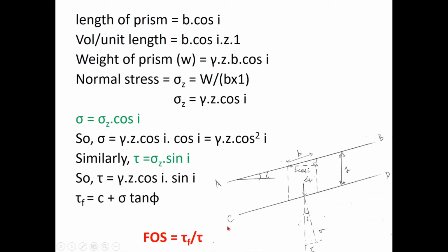Okay, so stability of infinite slopes or translational failures, we saw this figure yesterday, and we derived the expression for factor of safety in terms of shear stresses, right? You remember this derivation? We saw the basic concept yesterday. We found the weight of the wedge, the driving forces, and the normal stresses. We resolved the reacting normal stress and shear stresses we calculated. And in terms of the shear strength of the soil and the shear stresses due to the slope, we found the factor of safety against failure. This we saw yesterday, right?